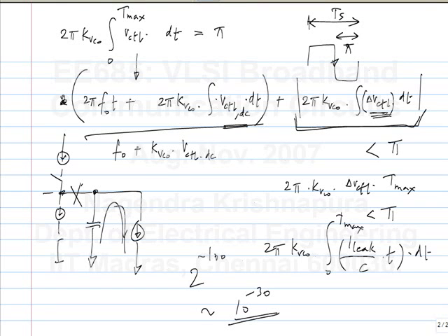But then, let's say you are operating at 1 megahertz, then 100 symbols is how much? 10 microseconds. Sorry, 100 microseconds. So 100 microseconds is a long time, okay? So there, actually, the leakage current can be a problem. So it depends on a lot of other variables. So there is leakage current and there are other errors that can be injected and so on.